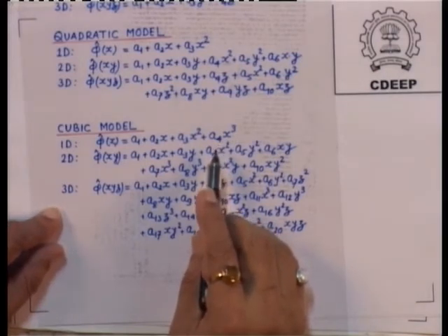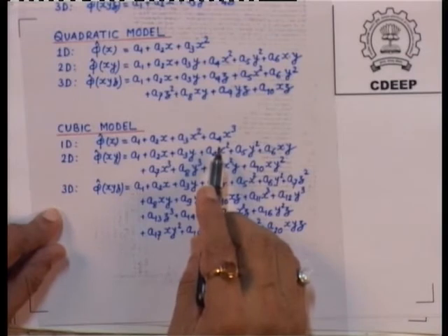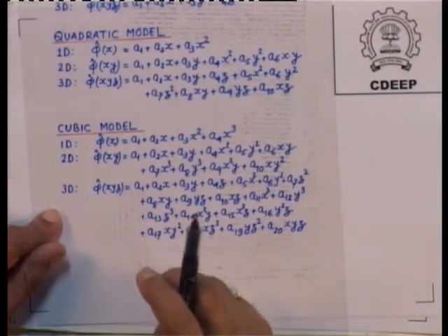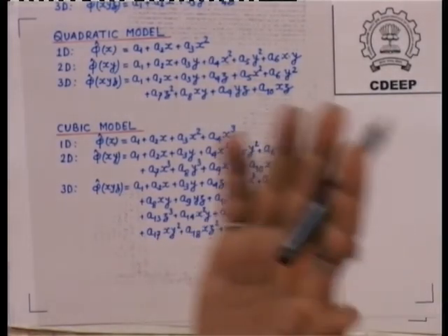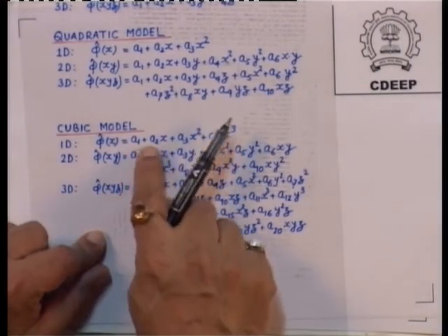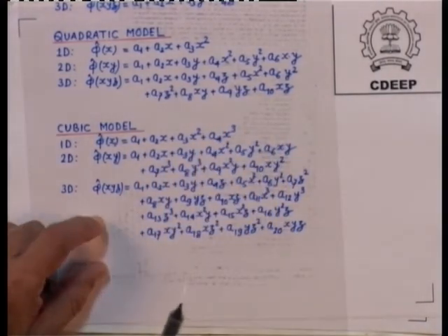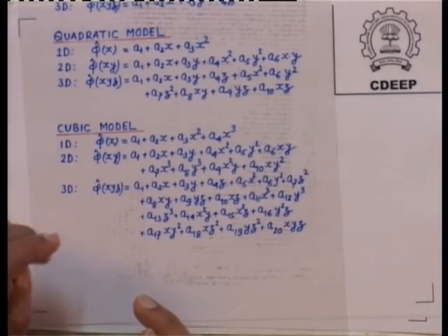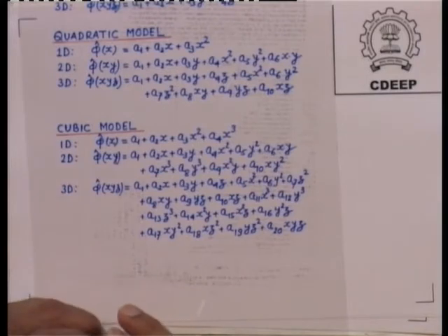And same thing, supposing you want to start with the cubic function. So, the first will be this in 1 dimension, in 2 dimension it will have this. So, that means you need 4 constants, 4 nodes. That is why the basic element is a tetrahedron in 3 dimension. Basic element is a tetrahedron, 4 noded, 4 faces, because there should be as many coefficients as there are nodes.